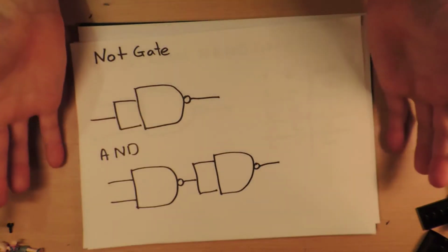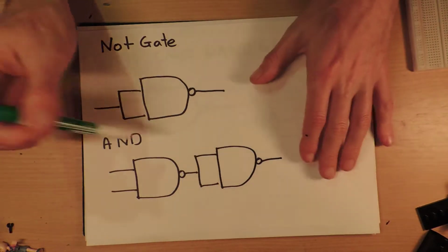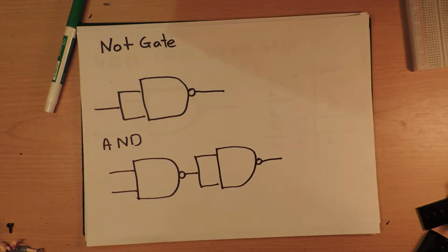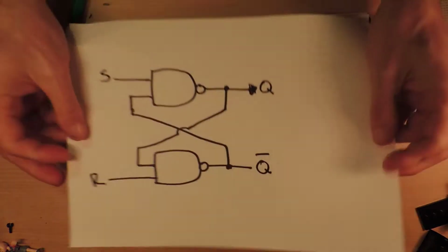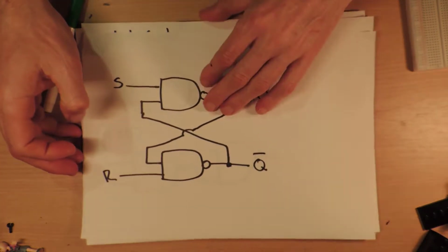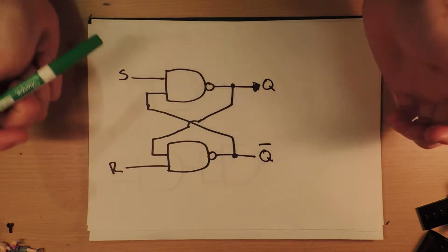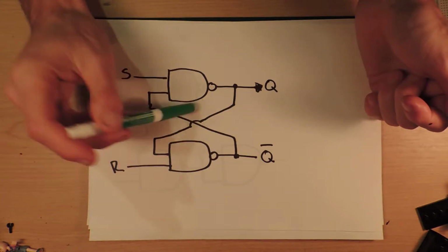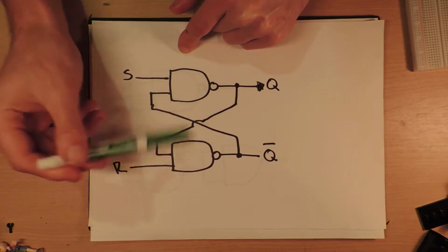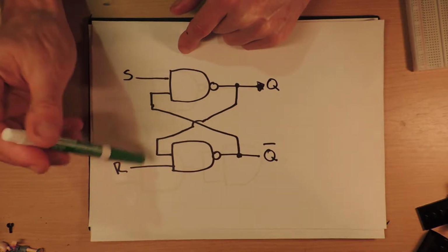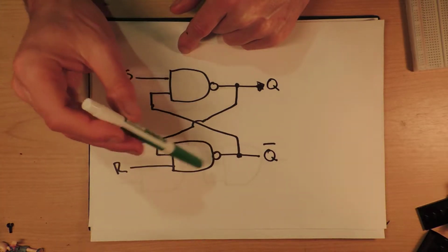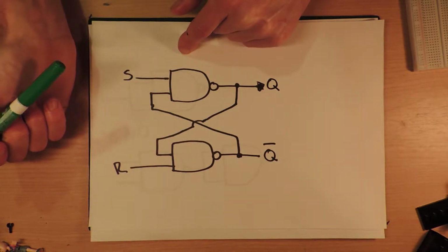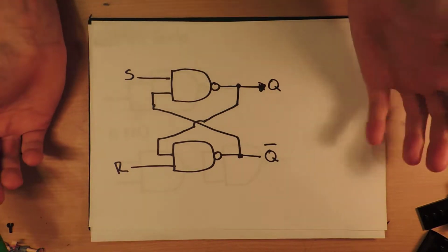But with one more of these things, you can make an OR gate, and you can make pretty much every single kind of gate you want out of these things. Plus, you can make some other interesting things. The thing that we're going to make today, just very quickly, is another set and reset flip-flop circuit. This is kind of like what we did with the 4049. Nobody ever does it with the 4049 because it's simpler to do it with this thing here. My 4049 circuit had a couple of resistors thrown in and diodes on the inputs, so it was a little bit more involved, but it does work, right? And that's the important thing.